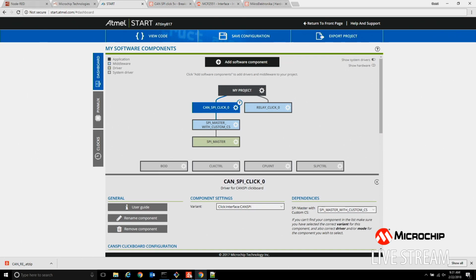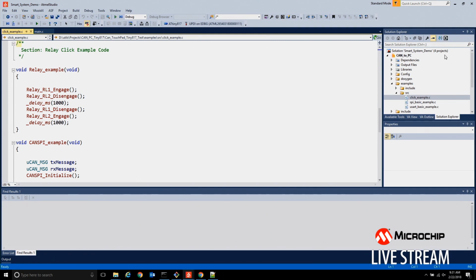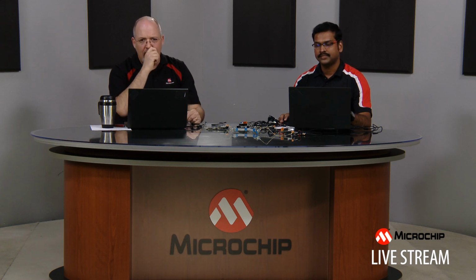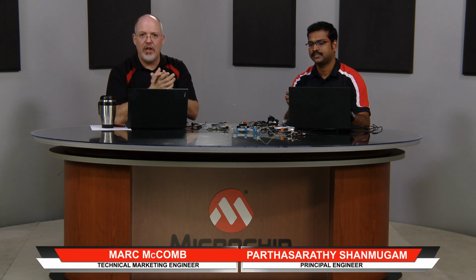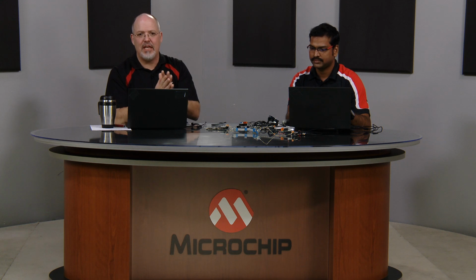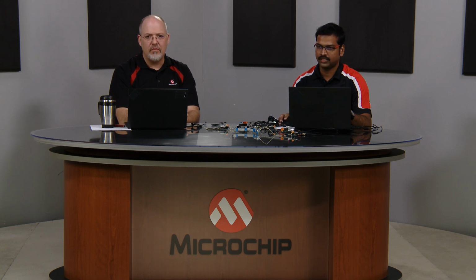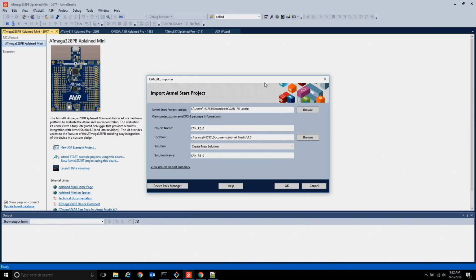Okay, so back to the modules. Sorry, back to the interrupt module here. Now, just to let viewers know that between Start and what you see here, there's a couple more steps. You're going to set up your project obviously the way you would any other Atmel Studio project. Where's my project going to live on my PC? What am I going to name it? Is it going to be part of a solution? That kind of thing. But it's pretty straightforward. We've already done this in the interest of time. Can you switch to screen? Yeah, this is the dialog you will get prompted with when you import the project. It will show you the path, the file name, and project name for Atmel Studio.